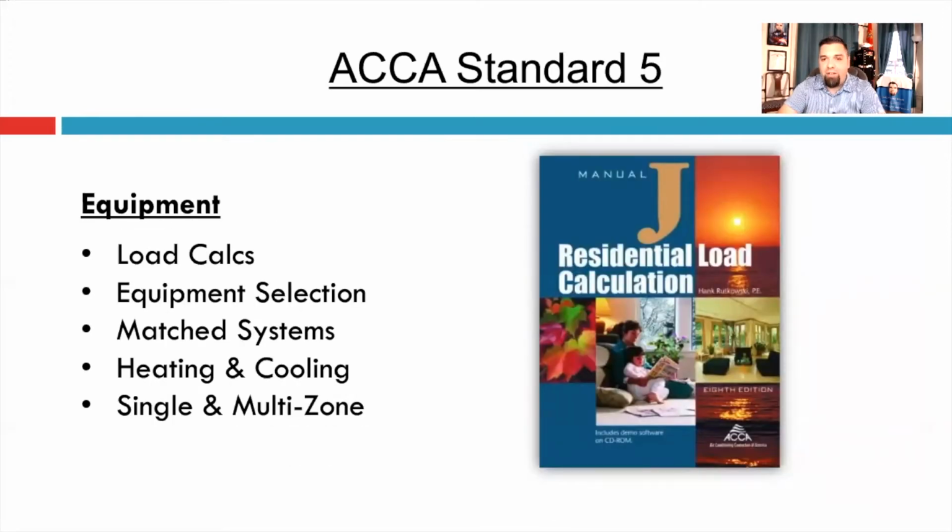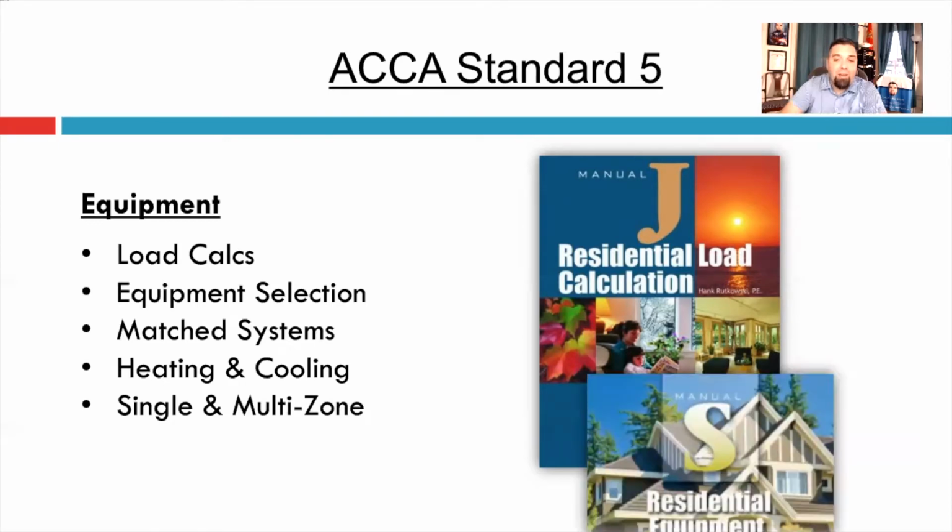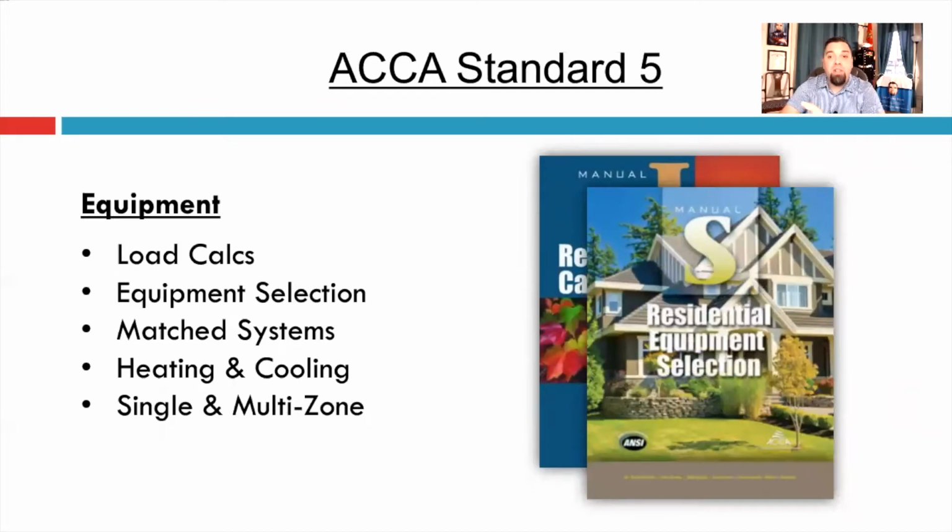So with equipment, this is probably a broken record coming from me here, and probably why most of you guys are on my Patreon site, but you got to do a load calc. All right, so you got to do a load calc properly, and you need to select equipment using ACCA Manual S and be within that standard, okay? You need to sell matched systems, which have an AHRI certificate, right?